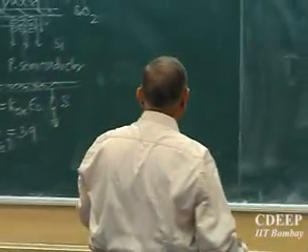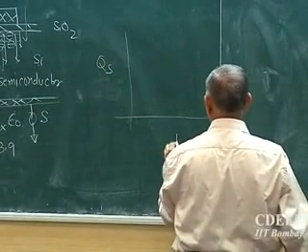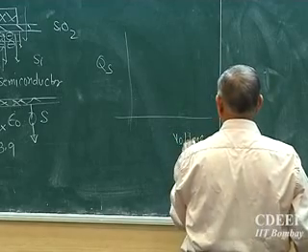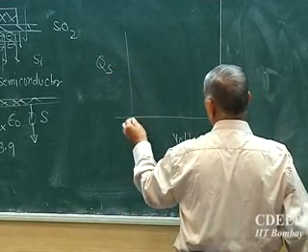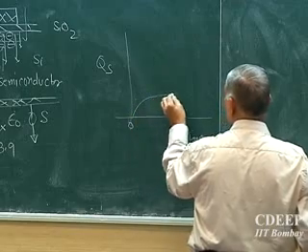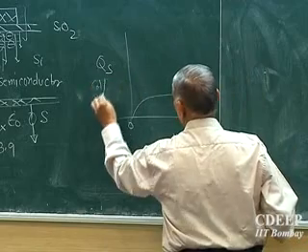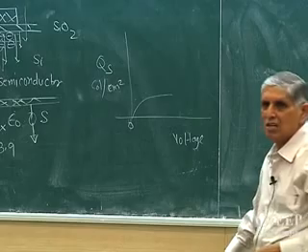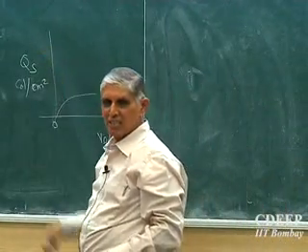And then we say that any time the charge has to, if you draw a figure, not necessarily a very good figure, the semiconductor charge versus bias or voltage VGS, let's say positive, this is for this device. So I figure out initially this charge QS, charge is always defined as coulombs per centimeter square. Please remember this is charge density. You have to always multiply by the given area. How much is the area here? Can you tell me how much?